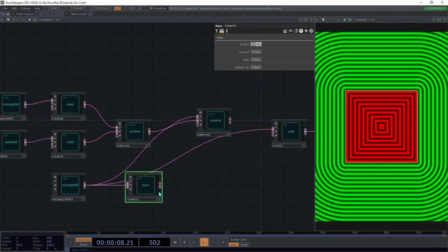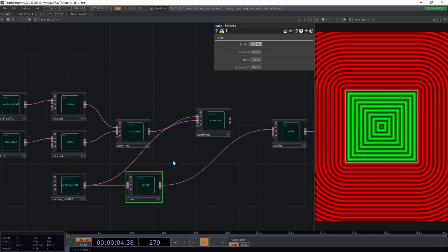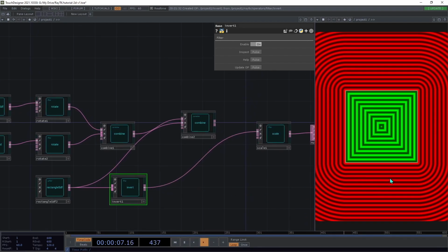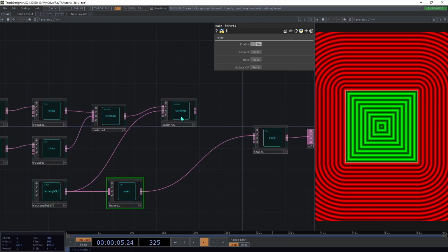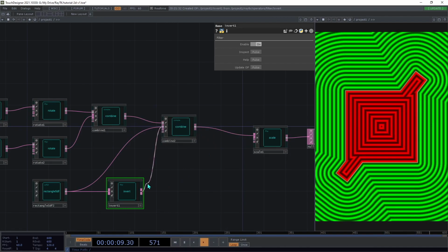And so right now, what we're seeing here is the shape where the red area is the inside of the shape, green area is the outside of the shape. So what invert does is it flips those two. So you can see there, this outer area is now what it thinks of as being inside the shape, and the inside is what it thinks of as being outside. And if you're using this in a 3D context, you can use invert with a box SDF to make a hollow room, which can be a good element to set scenes inside. You just need to make sure that the camera is somewhere inside it, so it isn't being blocked by the walls of the cube. So going to connect this back up here and go back to that.